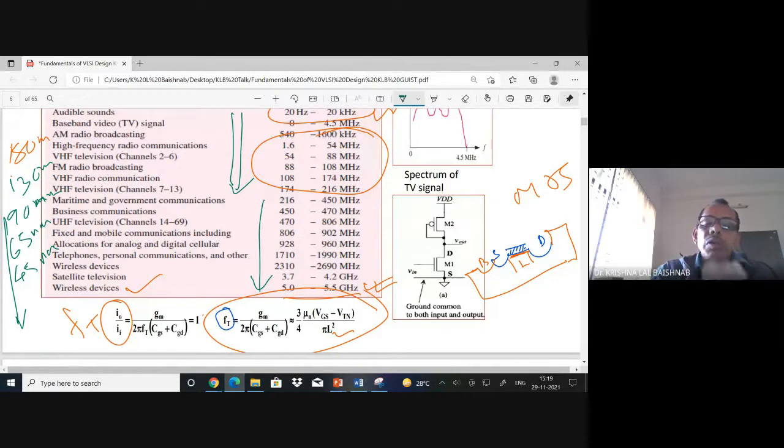So why are people going for high frequency? One is line of sight communication. At low frequency, it is sky communication; we have reflection on the ionosphere, then it will go on spreading. And at very low frequency, it is ground wave communication. So people go for line of sight communication at the gigahertz range, higher megahertz range. So line of sight communication is preferable.